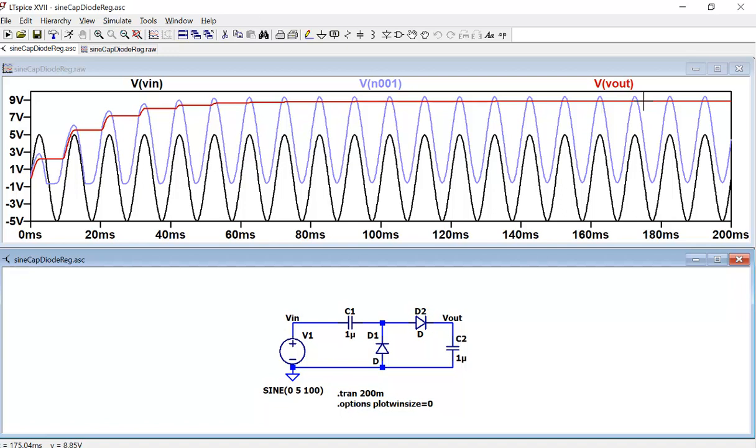Because right now we are trying to make a high voltage power supply. You don't have to make it high, you can directly just use a rectifier, right? And it's going to be whatever the voltage is here. So whenever it rectifies it, it's just tracking the top voltage here, right? Just smoothing out the oscillation over here, but it's not giving you a high DC voltage.